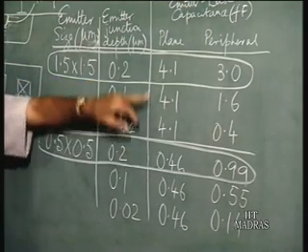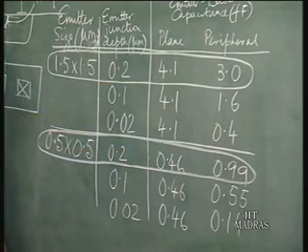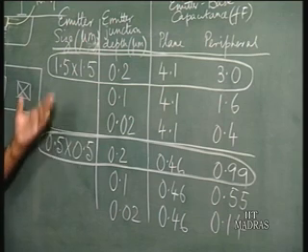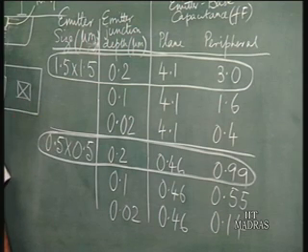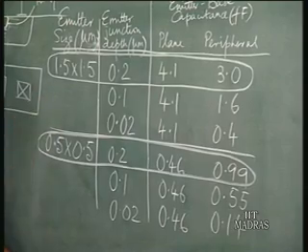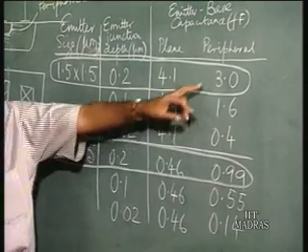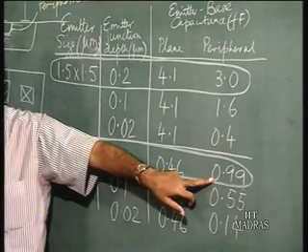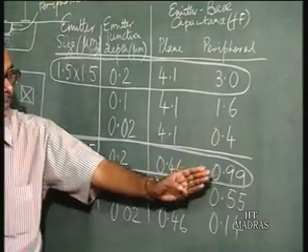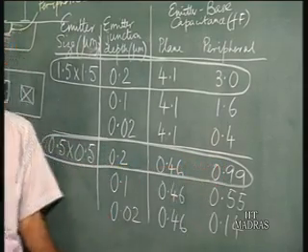Correspondingly, the plane part of the capacitance has reduced from 4.1 to 0.46. So, this has been reduced to 1/3, so the capacitance would be reduced by 1/9 area, 1/3 on each side. The capacitance is just proportional to area. But you see the peripheral component has not reduced by that much. In fact, the peripheral capacitance is much higher than the plane capacitance.